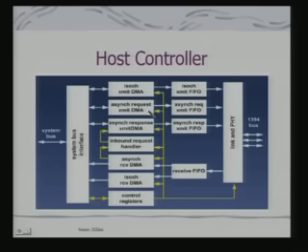Other buses will also have a conceptually similar interface architecture. So here you find that for each one of them I have indicated the DMA channel, and you have the control registers. In fact, these control registers will essentially manage the overall DMA transfers. If it is really a DMA request, so that a processor should relinquish the bus and data get transferred, that information will be generated from here, and what is the location where the data has to go, etc. All this information will come from control registers.